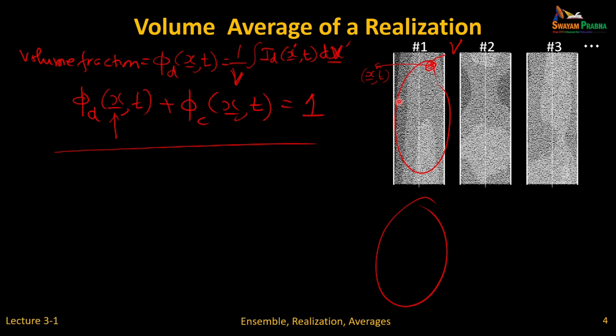So in other words, you can average over all the particles in there, or you can average over all the fluid in there. So you can define, say, volume fraction occupied by the continuous phase, volume fraction occupied by the particulate phase. Say, for example, for the volume fraction of the dispersed phase particles, you could take an average of the indicator function and you can get it. So this is a simple way of averaging, sort of coarse graining.